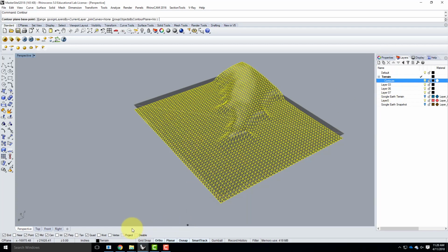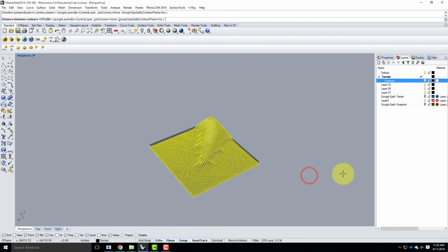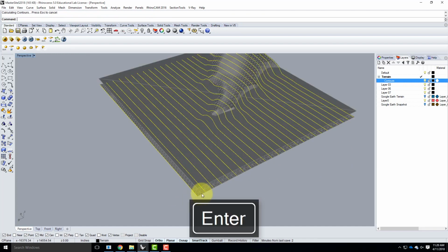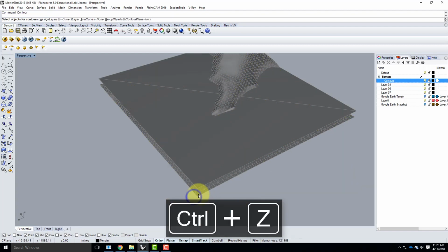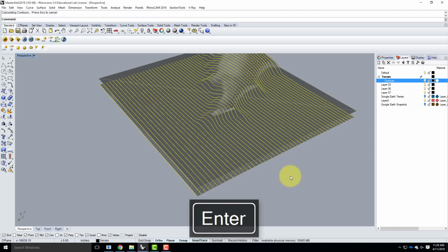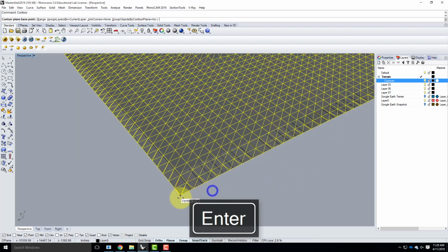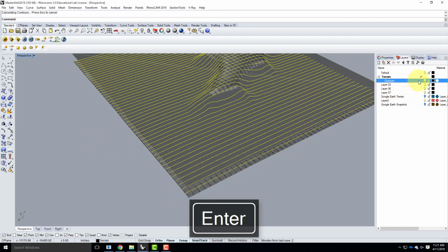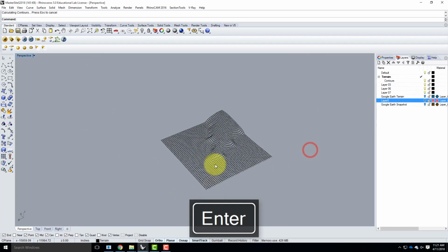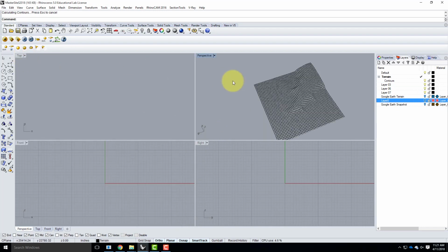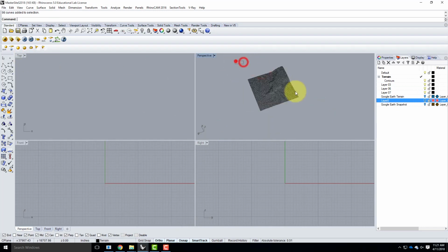And I'll do a contour. I'll select my base point. I might have to turn on vertex to be able to snap to that corner. There we go. We're going off in this direction. I'll do it at 100 feet. And let me do it a little tighter than that. Let me do it at 50 feet. We'll go in this direction by 50 feet. We can turn off layer 0, and now I have all of my lines, my contours.